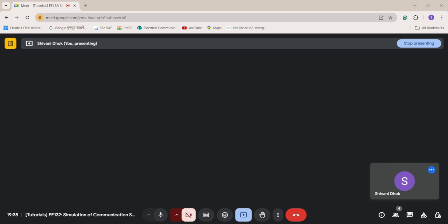Now next what we need to do is get N random constellation points for transmission. Okay, so for that we'll take our standard trick: index rand I. So these will be between 1 and M, and how many do we want? N comma 1.